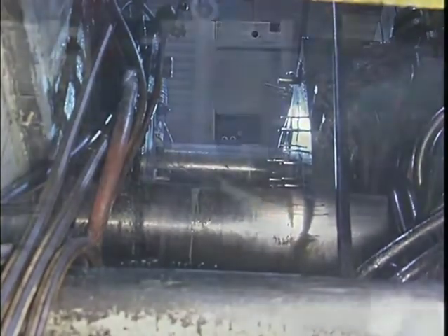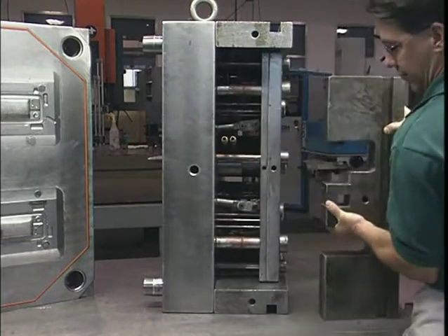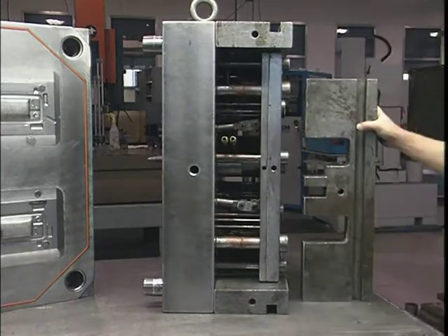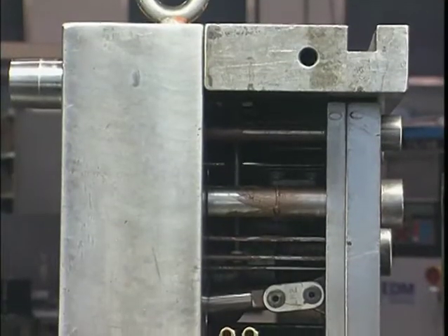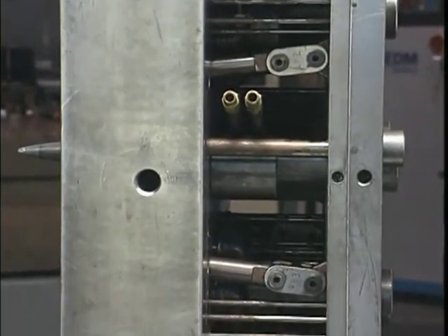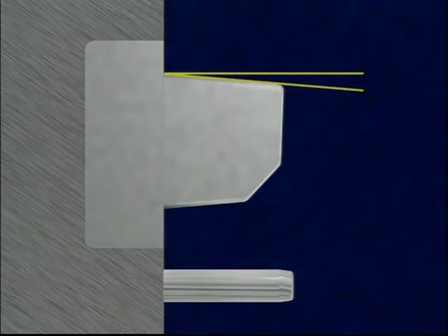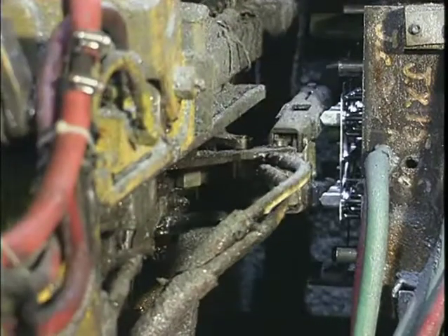In the system, ejector pins are mounted between ejector plates in a pocket on the ejector side of the die. In most cases, they are activated by pneumatic or hydraulic cylinders. To facilitate casting ejection, dies and cores incorporate a slight draft or taper, the amount depending on the metal to be cast. In general, the lower the metal's melting temperature, the less the draft required.